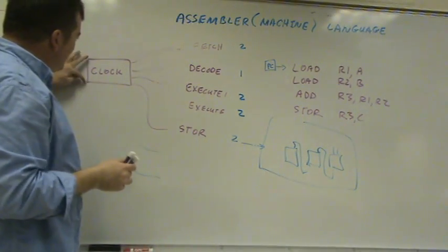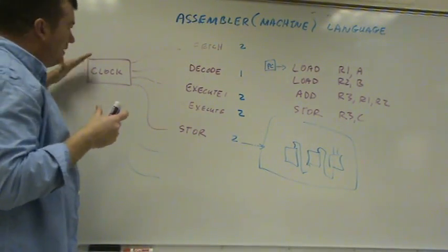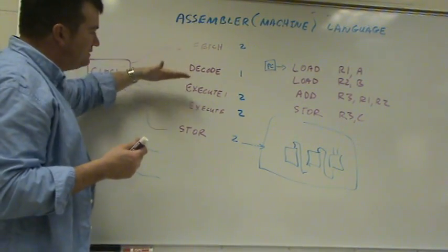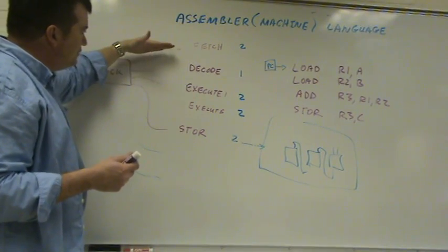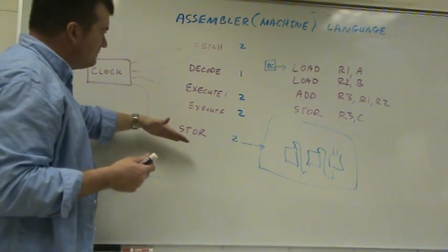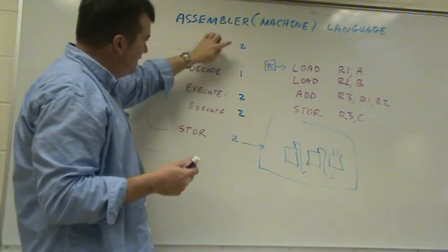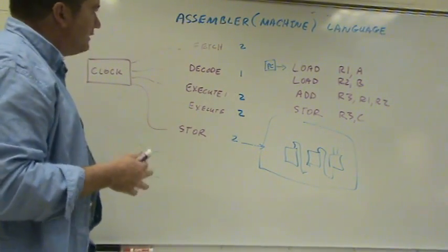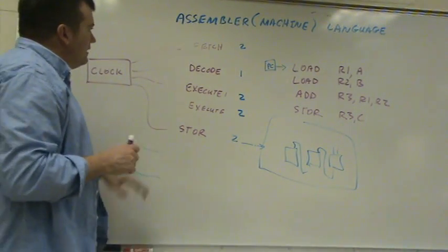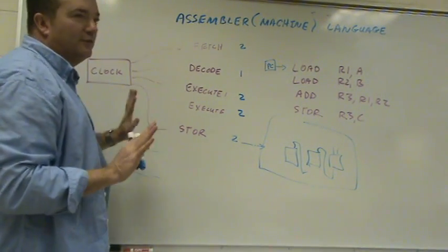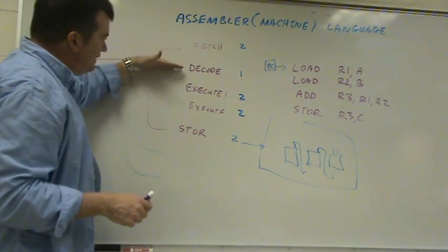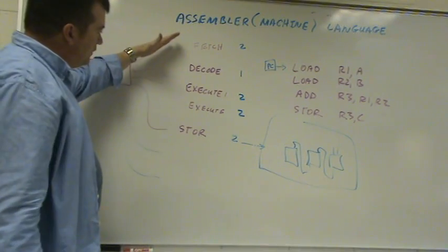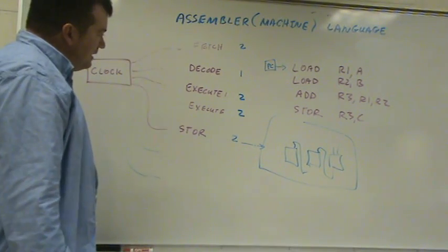And then, since we control the speed of the clock, we can make the clock as slow as the slowest step. So now the clock can go every 2 milliseconds for each of the steps. And now an entire instruction could take 2, 4, 6, 8, 10. It would take 10, because we'd have to give the decode step 2 units as well, because everything gets the same amount of time. So yeah, now we went from 16 to 10.